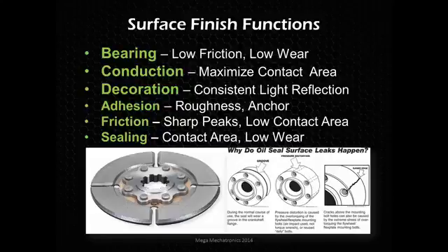or the flywheel. And that can actually cause distortions, which will cause leaks in areas where, when that crankshaft is spinning, the rubber seal is not flexible enough to close those gaps, just from the inertia of the seal being open and closed so quickly. And then obviously cracks can cause leaks.